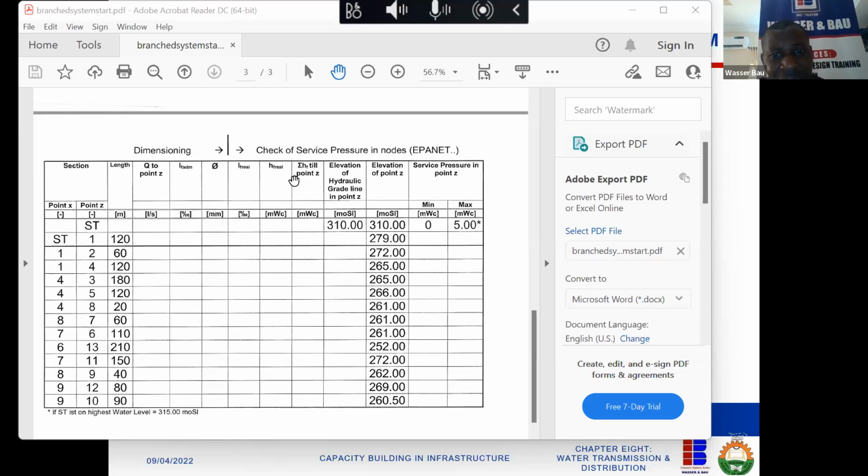Those of you that are mechanical engineers, sometimes when you design the hydropower systems and it gives you a turbine with a head of, you design a system and it gives you a pump. Your pump of 15 meter head will take it. You, the engineer, will go and provide 20 meter.